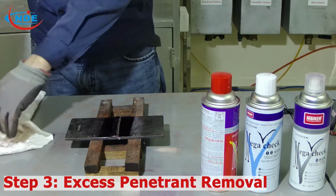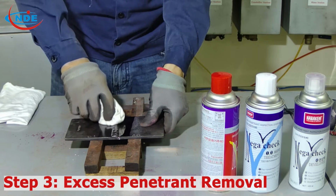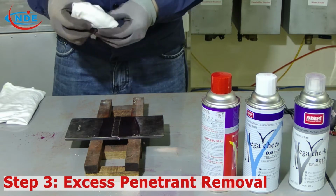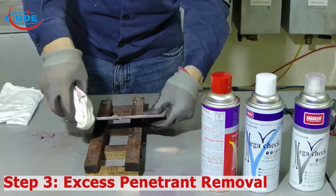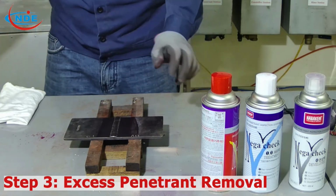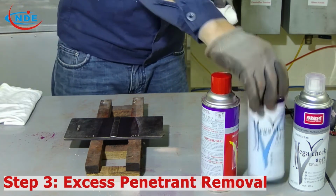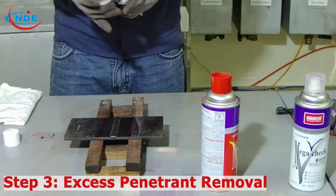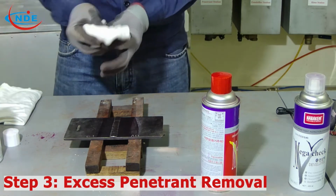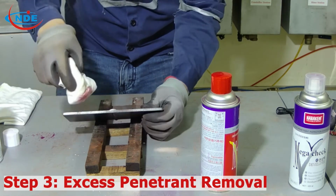Step 3. Excess penetrant removal. Excess penetrant can be removed by wiping with a clean, dry cotton rag or absorbent paper. Repeat the action until most traces of penetrant have been removed. The remaining traces should be removed by wiping the surface with a clean rag lightly moistened with solvent. A white rag is recommended to observe a better removal of the excess penetrant.